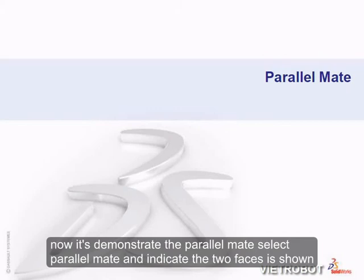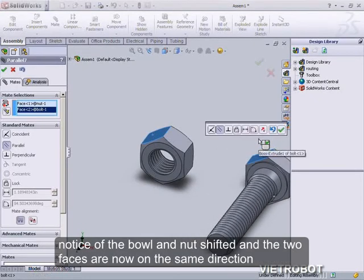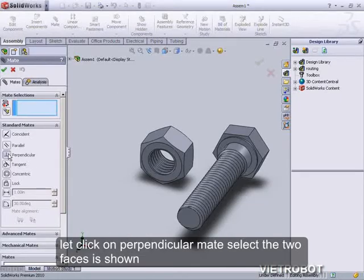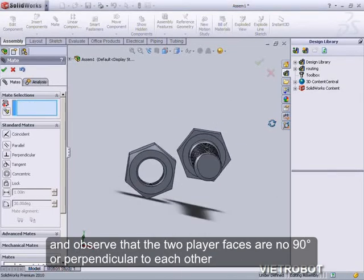Now let's demonstrate the parallel mate. Select the parallel mate and indicate the 2 faces as shown. Notice that the bolt and nut shifted so that the 2 faces are now in the same direction. The perpendicular mate defines a 90-degree relationship between the 2 entities. Let's click on the perpendicular mate, select the 2 faces as shown, and observe that the 2 planar faces are now 90 degrees or perpendicular to each other.